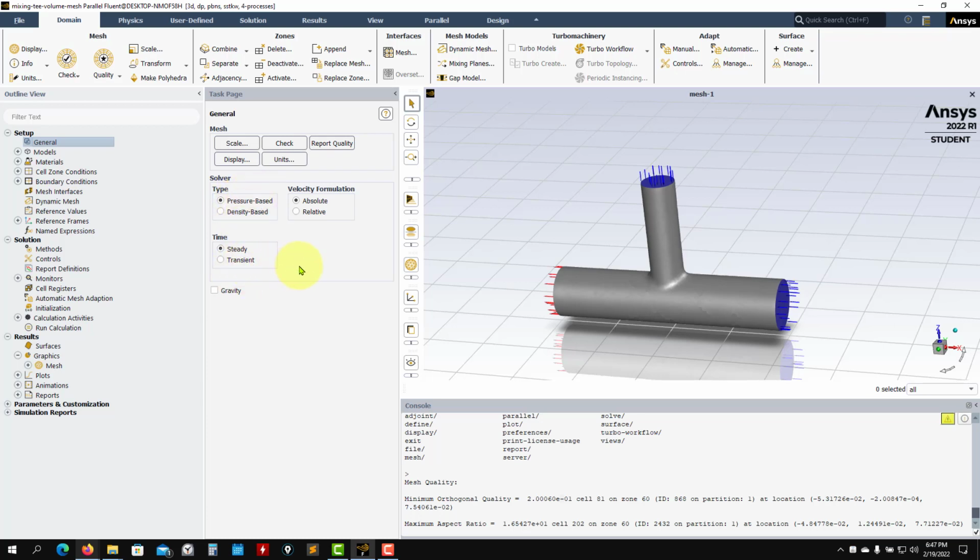Then also you can choose the discretization. And this is a hypothesis, by the way. So later also we're going to talk about this hypothesis. You can assume that your flow is steady, or you can also assume that you have a fully unsteady transient flow. Okay, so if you take this hypothesis, steady flow, it means that you don't have any vortex shedding, or you are saying that it is something that you can neglect. In our case, steady hypothesis is okay.